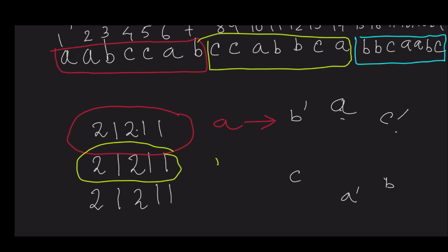So you can say that this is for C, and this group, first two conductors will start with C, next one will be what? You should make a complete turn, once it is over A, B, C, then again A will come. So 1 will be occupied by A, then 2 will be given to B, then again 1 should be given to C, and the next one should be given to A. Now the last one, the same thing is happening,